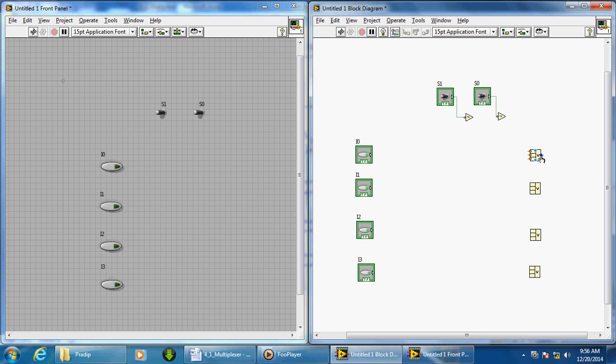So what I have to do is just click on this V letter, it will give you change mode, and then make it AND gate. Do it for all. Now it has become 3 input AND gate.